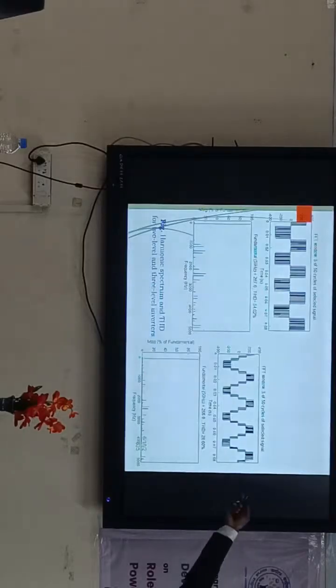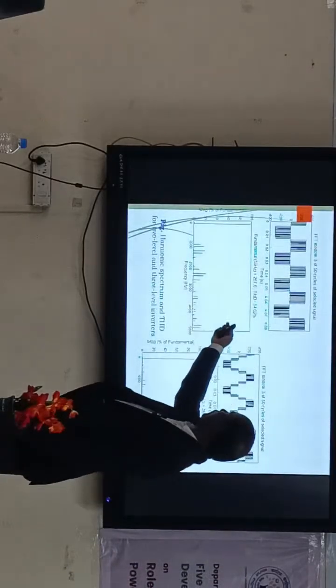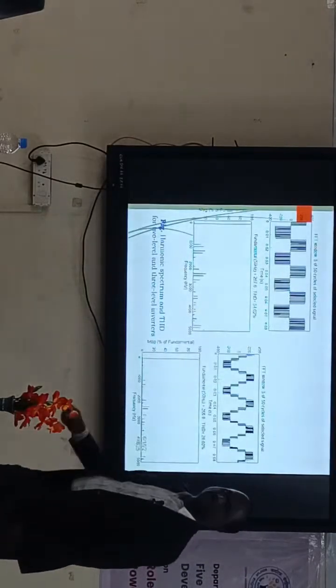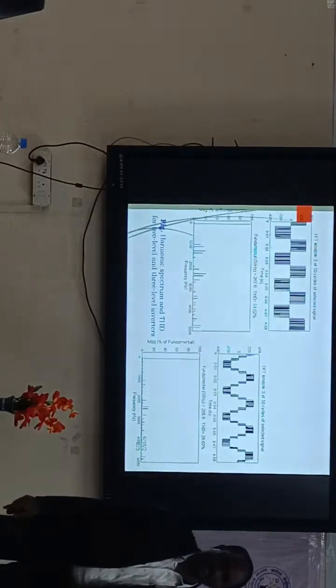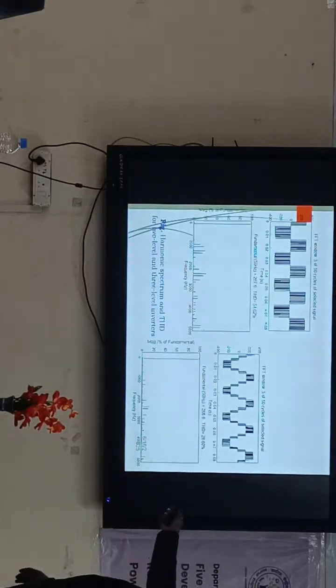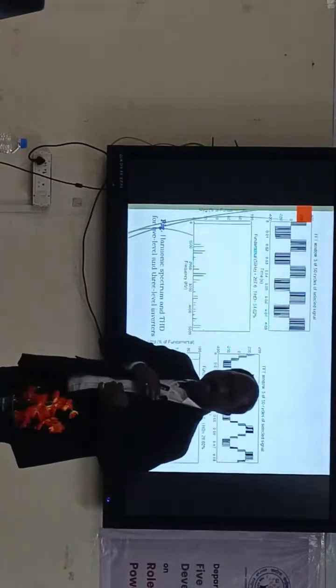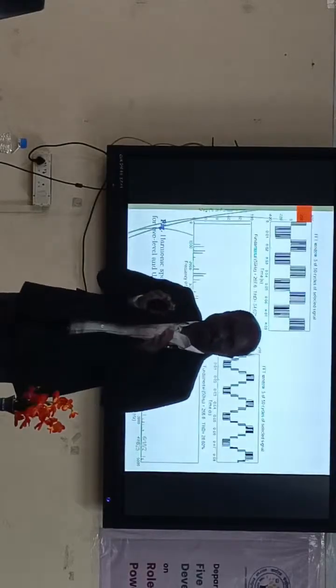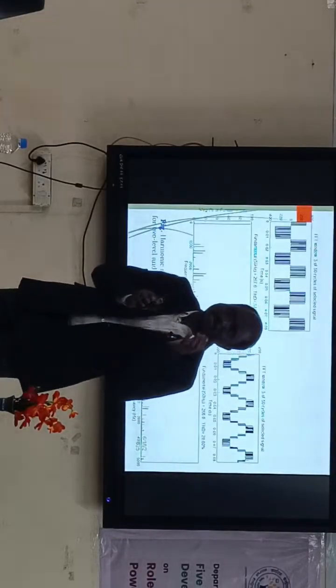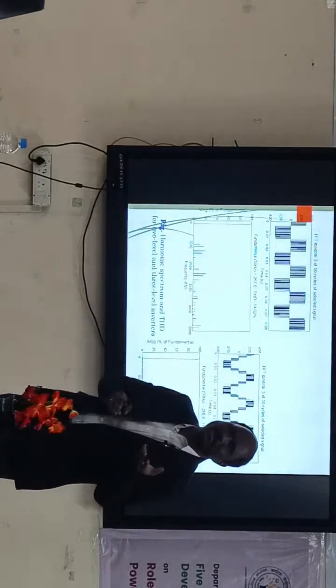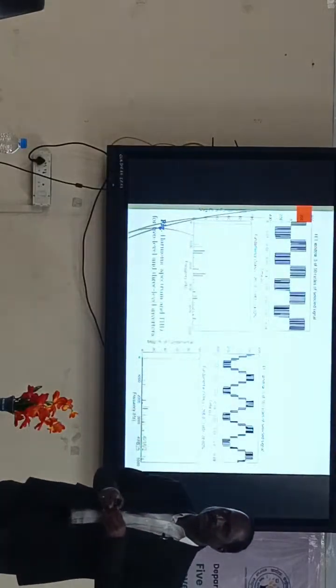This is the 2-level inverter, where we got THD as 54.0, more than 50% disturbance. For the 3-level inverter, it is coming to 28%. So what we discussed is only the conventional space vector, very basic. Based on this basic concept, we are implementing for the higher levels.